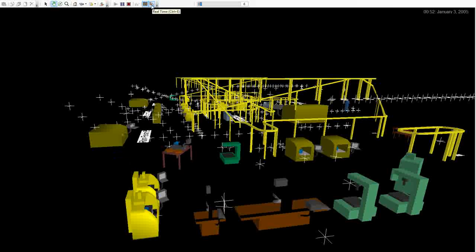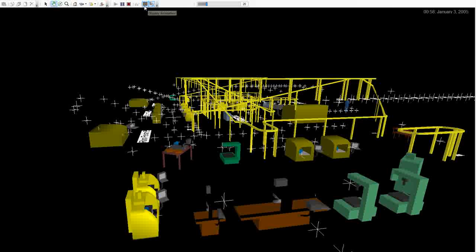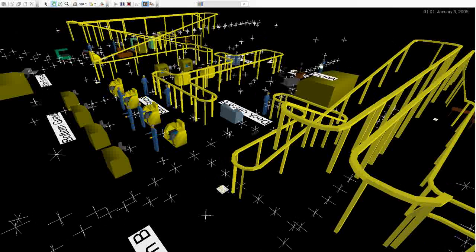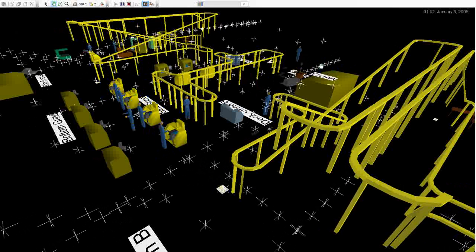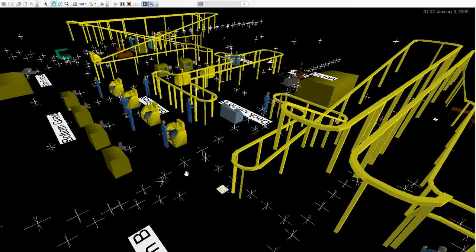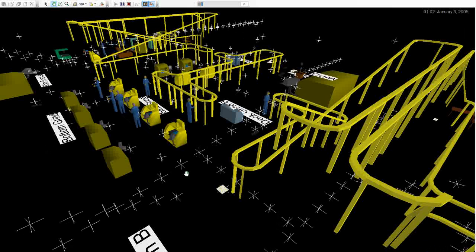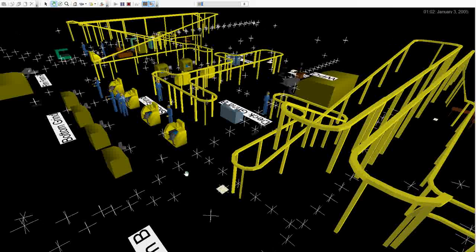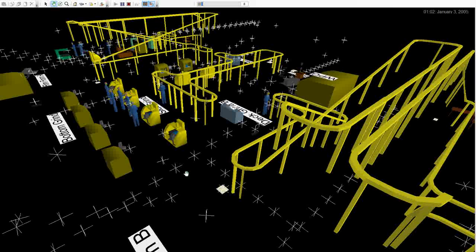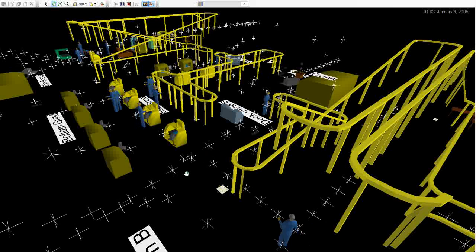Let's take this out of real time and go back a little bit to speed the model up again for you. So this customer was looking for a simulation-based solution so that they could study the capacity and constraint issues going on here, particularly in their grinding, buffing, and finishing processes of their facility. Some of the key questions they wanted to answer were around the capacity of the system, where the bottlenecks and constraints were, but they also wanted to take into account all the variability and the variations with the processes and changeover times, failures of equipment and equipment downtimes, as well as their manpower availability.